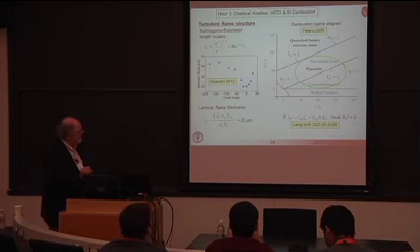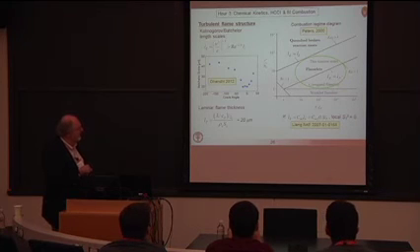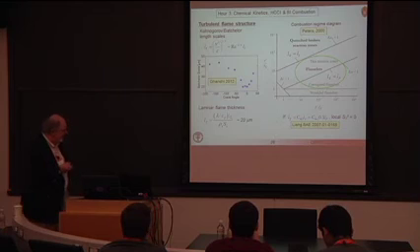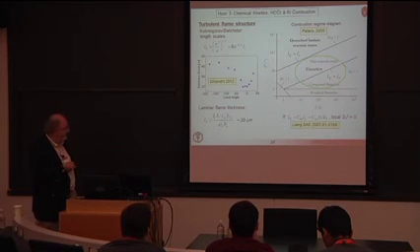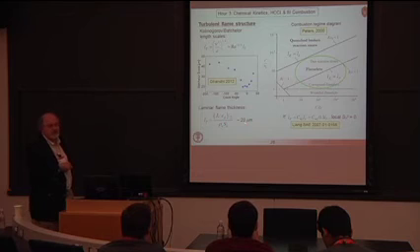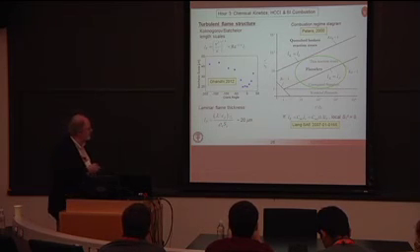So one of the important questions is to determine what is the flame thickness in an engine, like a laminar flame thickness. And you can estimate that from Mallard-Le Chatelier theory. It turns out to be about 20 microns. That's the thickness of a laminar flame under engine conditions.